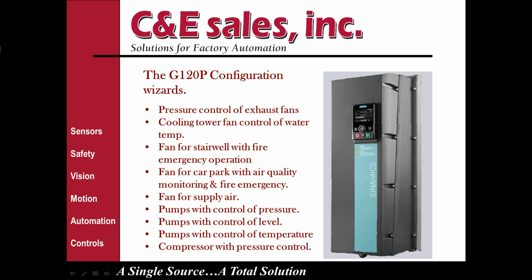This can save you quite a bit of energy, so that if the water coming back is already pretty cool, you can throttle down the fan automatically. As the water temp increases from a heavier load, you can bring the fan speed up. That can all be controlled directly by the G120Ps.